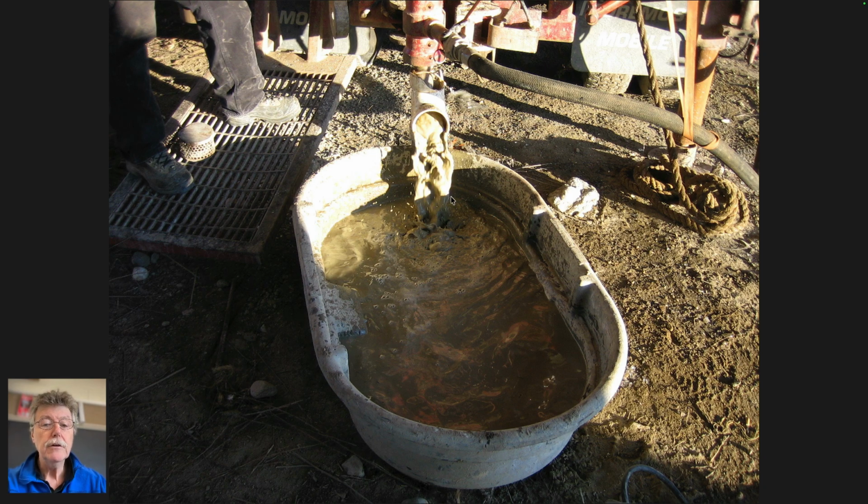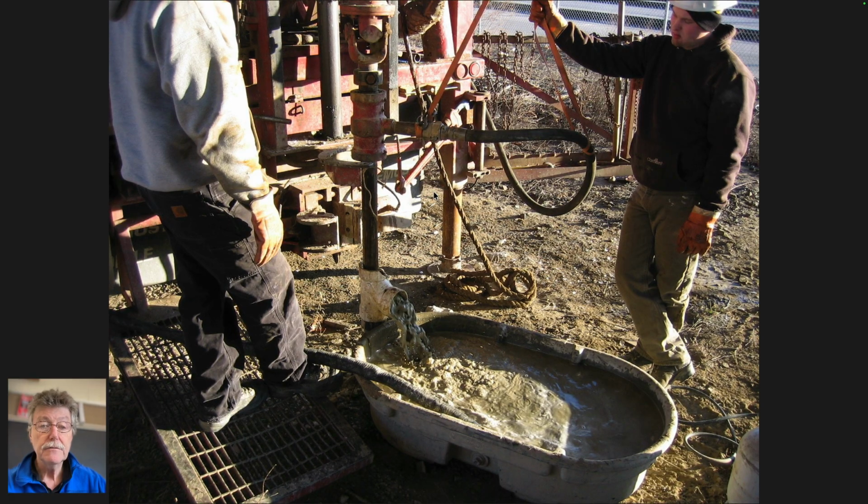So if you put a household sieve underneath here, you'll catch a whole bunch of pieces of rock, which are the size of the tip of your little finger, which you can then tell whether you're in clay or sandstone or whatever. So that's very low key. That's exactly what's happening here. So drill fluid in here, down the inside of the pipe. At the pipe joins, these little pieces of string are put around the threads so that when you screw it up and tighten it, it seals it against the water. So the water is trapped in here as it goes down. It doesn't leak out into the formation.